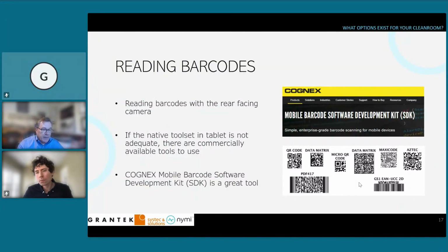And if you have an area in your facility where maybe you're mixing minor ingredients or doing something where it's going to be added to a larger batch later, you put it in a container, you can print a label that's both alphanumeric, so it's readable by the operator, but you can also have a 2D barcode which has the same information. When that shows up, the operator can just scan that 2D barcode, recognize what it is, compare it to what's in the batch record, make sure they're adding what should be added at that point in time, capture it and move on. So it's a great way to automate another piece of the process, put it in your batch record, have it done accurately and automatically, and it's done immediately. So it's immediately into your MES system. Next.